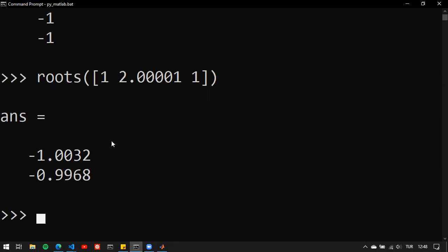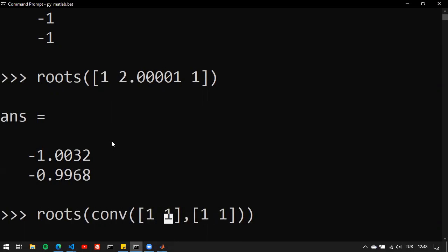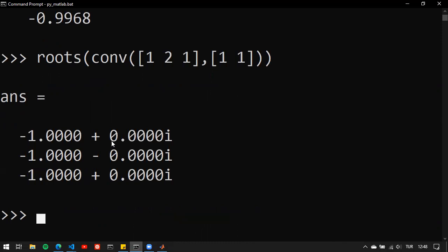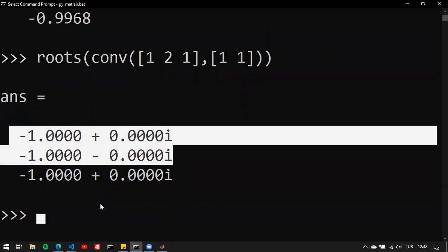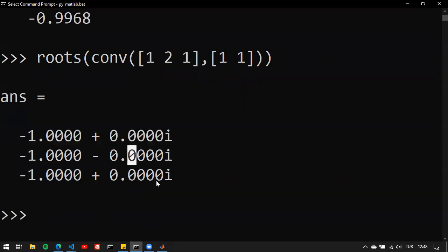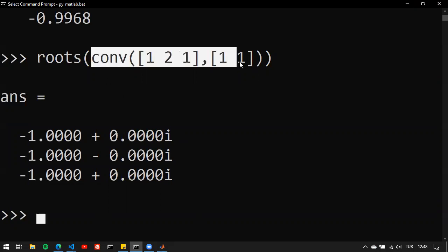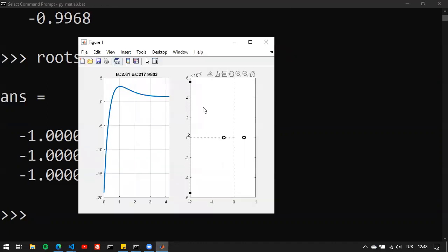And if you have, for example, a third order one, let's change it to this, you'll see that MATLAB also displays here some plus minus because they are conjugate pairs, and then there's a real part, but they are on top of each other. But this becomes more and more numerically sensitive. Therefore, sometimes if you use pzmap, you'll get some 10 to the power of -8, something that's negligible, that's really small. Therefore, what we can do is just update the y-axis in order to see that they are in fact on the real axis, not really on the complex axis here.